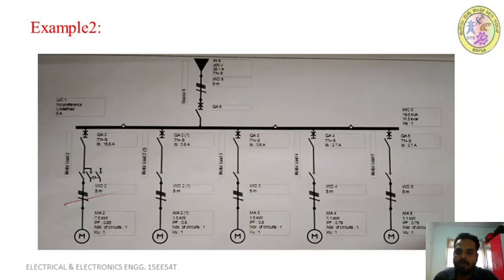Here you have taken the 3-phase supply and it is given to this main board. In the main board you may have an energy meter, a main ICTP switch, an ELCB, an MCB and indicators, and after that it is given to the individual switchboards. Each individual switchboard consists of an individual switch, that is ICTP of individual rating, an MCB, a capacitor bank and a starter, and from the starter it is connected to the individual motor terminals. This is about motor 1, where we are using a star delta starter, and motor 2 is the same case.